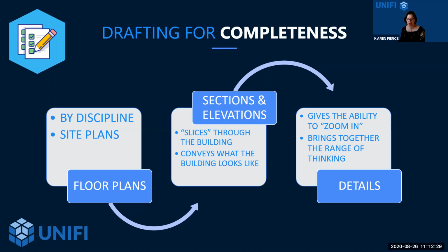Floor plans are generally produced as a cut through the building. Typically it's set at 4 feet, but you can always adjust that as you might need to. Floor plans might also include things like ceiling plans. So essentially really trying to visualize the layout of your building. And then you have sections and elevations. So basically trying to convey what the building looks like if I was to actually look at perhaps the interior wall elevation or the exterior wall.